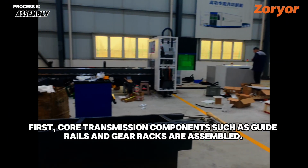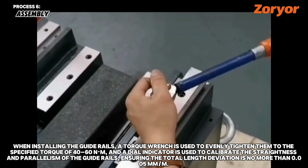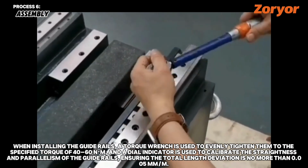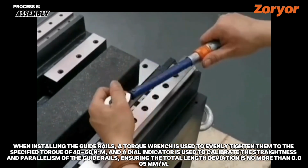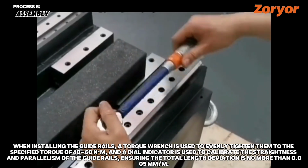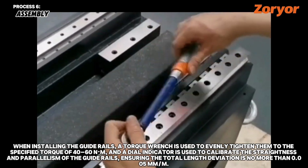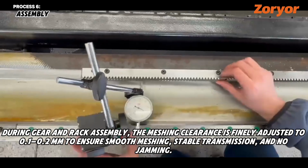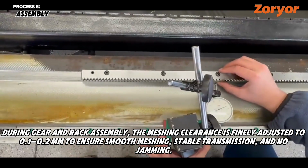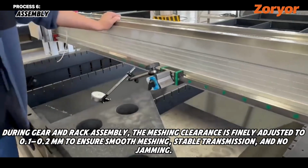First, core transmission components such as guide rails and gear racks are assembled. When installing the guide rails, a torque wrench is used to evenly tighten them to the specified torque of 40-60 Nm, and a dial indicator is used to calibrate the straightness and parallelism of the guide rails, ensuring the total length deviation is no more than 0.005 mm per meter. During gear and rack assembly, the meshing clearance is finely adjusted to 0.1-0.2 mm to ensure smooth meshing, stable transmission, and no jamming.